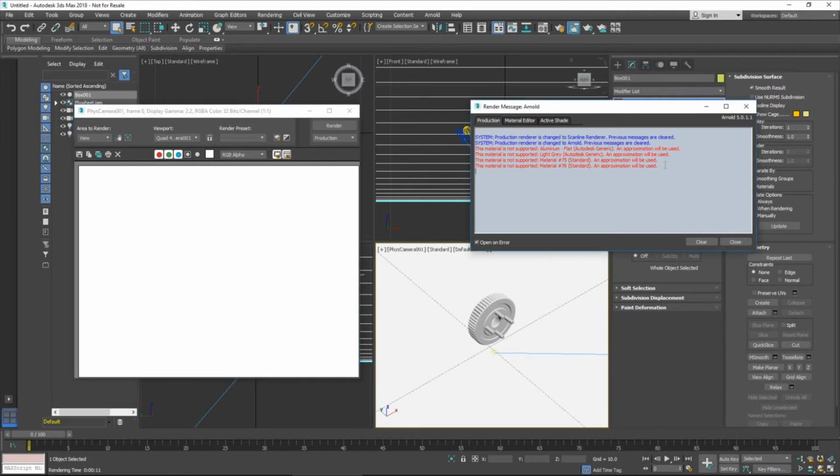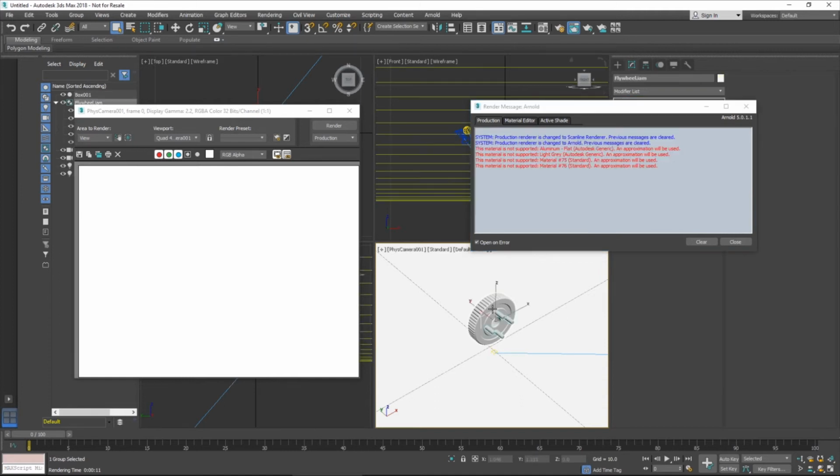As you can see, this actually happens because of the material that was brought in from Inventor by default. From Inventor we had the generic or the default material set to this flywheel, and the Arnold renderer actually can't render those materials. It's not set up to work with those. It's not compatible, so that's why we get nothing. And that's actually